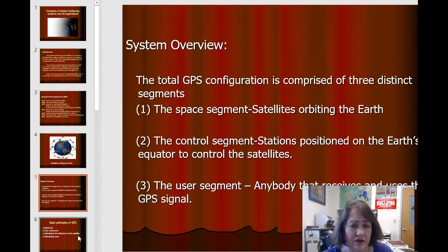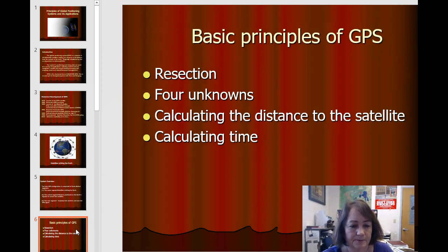And that allows you to really close in on the data to a pretty high degree of accuracy. So they're much more accurate than just a handheld, which may be only accurate to within a few meters, maybe 10 feet. So you can close in if you have a WAAS system. And of course, survey quality has the best data capabilities, the RTK, and the very, very high degree of accuracy. But once again, it's the same signal off the satellite.